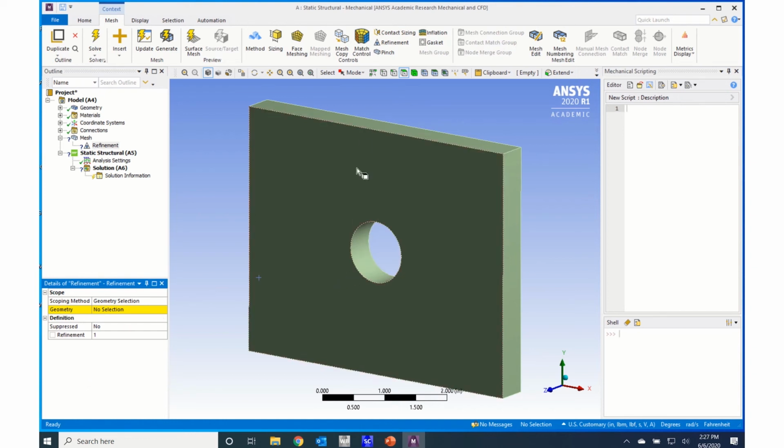So I'm going to come across the top here and use the selection guide. I want to select lines, so I'll select that icon, and that lets me just select lines. As I get on the line, it highlights it. I can click it, and then I can control and move to the back line and click that.